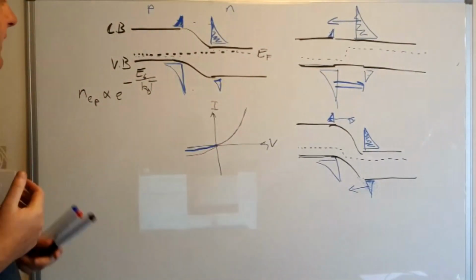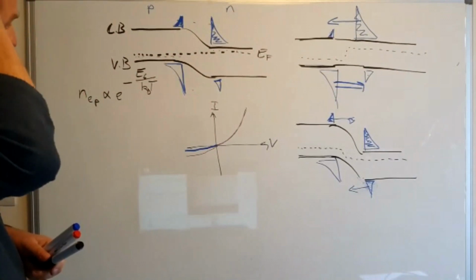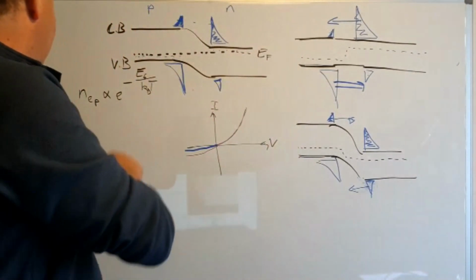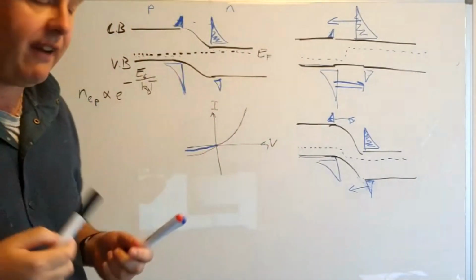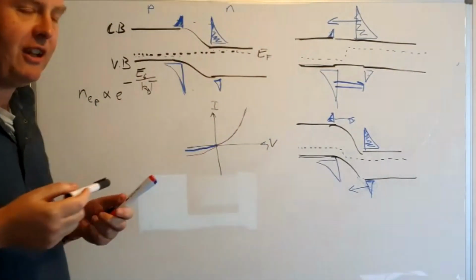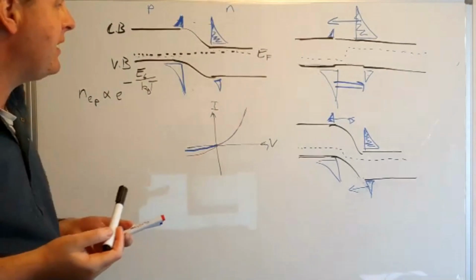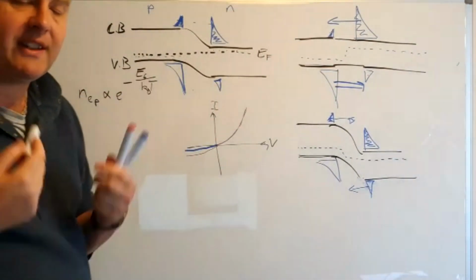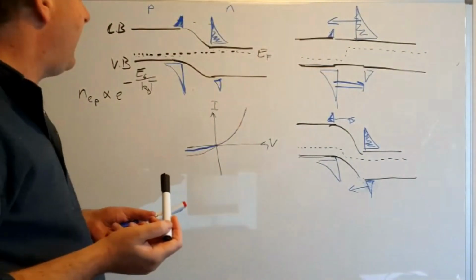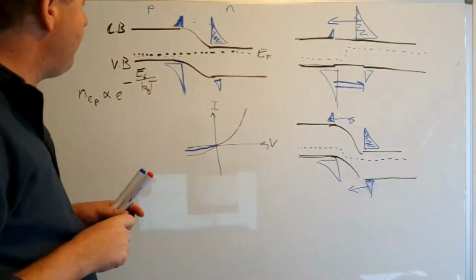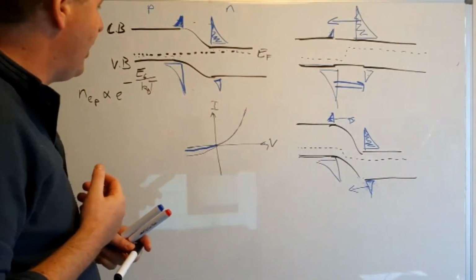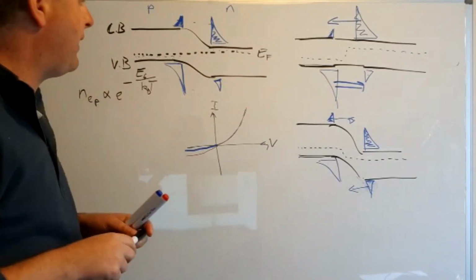Okay, great, so that's fine, except for one slight problem. And that is that in this situation, I've got a semiconductor, I've got a relatively small number of charge carriers, and therefore this sort of sensor is also going to be susceptible to the Hall effect. So if I try using this as a temperature sensor in a system with a magnetic field, then I'm going to get a Hall voltage as well. And that's going to interfere with my measurement of my temperature. And so as I change the magnetic field, it's going to look like my sample is changing temperature, but it's not really, it's just that I'm picking up a Hall effect.